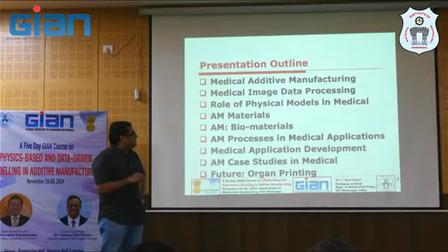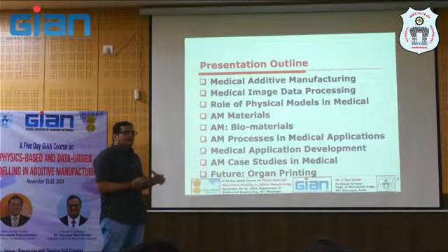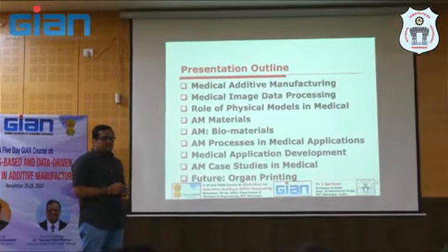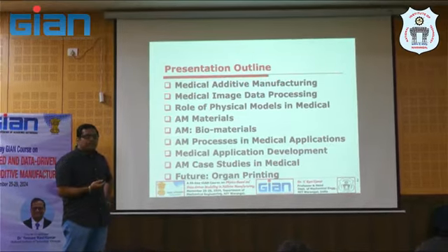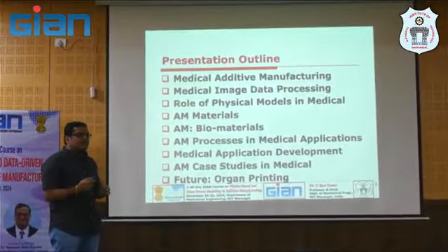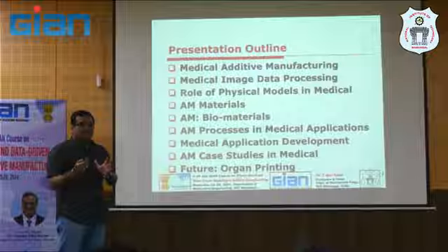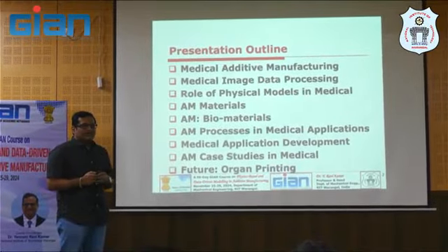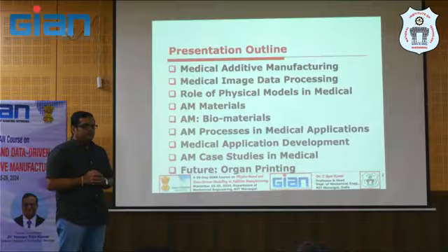Then those DICOM images will be imported to any one of the medical image processing software. In my talk, we have used the software Mimics, Materialise. You can use any medical image processing software to convert your DICOM images. Further, you can segregate your tissues from a whole bunch of tissues. You may be interested at a particular point of time in maybe bone, and you may not be interested in the soft tissue. Then you can segregate the area of interest as well as the tissue of interest.